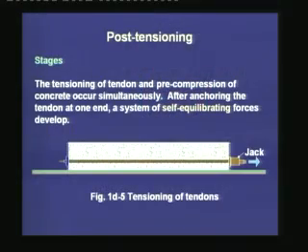Now, as I said before, in the pre-tensioning system, if we use a precasting bed and end abutments, it needs strong foundations. We can avoid strong foundations if we use a stress bench, which is a self-equilibrating system.